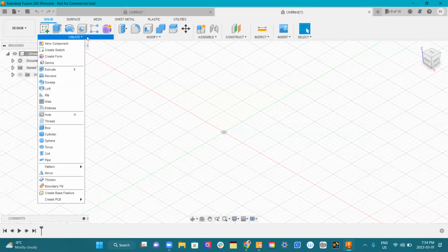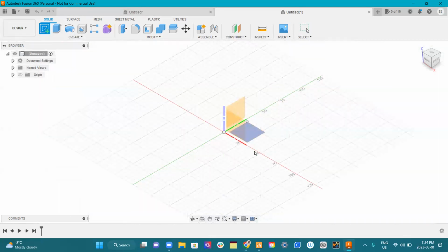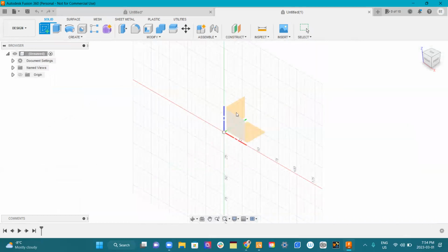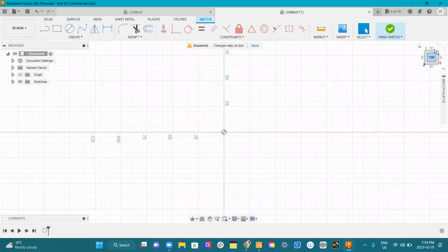The way that this works is a little bit different than 3D modeling programs, especially if you are doing sculpting. It's a totally different workflow. It's like, tell me how many millimeters the thing is, and you have to define all of the different areas. The way it works starts with a sketch. As I'm clicking around here, this is a flat plane that is moving in different directions. I've got a little box here that tells me about the top side, but it's kind of hard to see, but this says Z is blue, X is red, and Y is green. So when I'm picking this face and I click here, this says Y and X. So this here is X, this here is Y, and this machine has an XYZ as well.